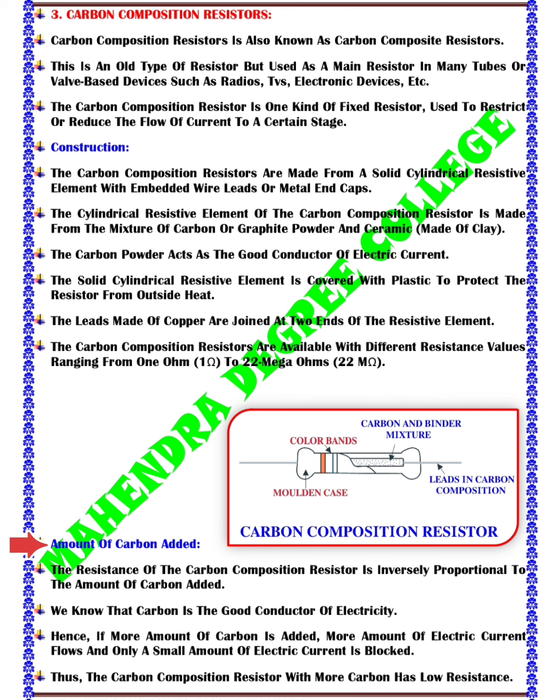Next, the amount of carbon added. The resistance of a carbon composition resistor is determined by the amount of carbon mixed with a binder material. Increasing the amount of carbon in the mixture generally leads to a lower resistance value. Less carbon in the mixture results in a higher resistance.